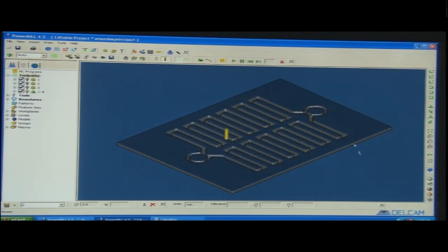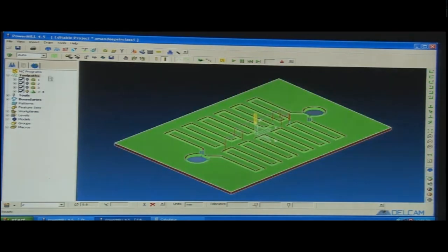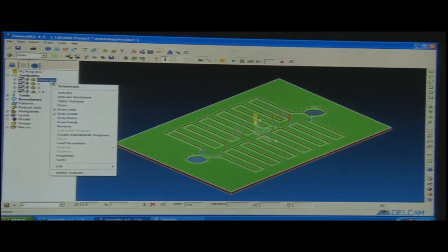So, it is choosing its path on its own and trying to finish the form, which is taking care of the finishing of the workpiece. So, in this way we generate the tool path. It is how the tool will move, how the tool interacts, how the tool retracts. So, we can also name our different tool paths, like I have just put a different name for that, so that we can recall the data whenever we like.